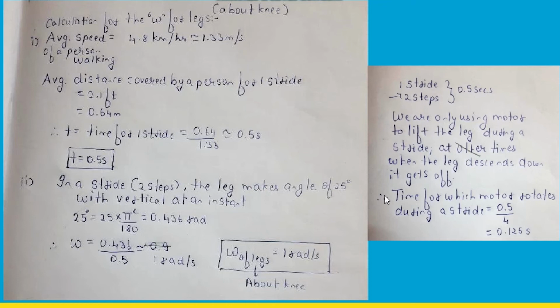From this angular velocity we know the decrease in the length of the string that is being pulled by the motor in a given time, and from this we get the linear velocity of the string, that is the linear velocity of the pulley, and with the help of the radius of the pulley we can find the angular velocity of the motor.